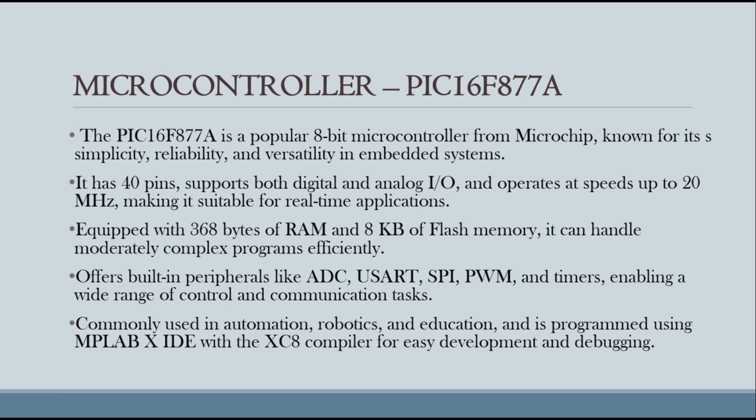Now we discuss the main component of this project, that is the microcontroller PIC16F877A. It is a popular 8-bit microcontroller from Microchip, known for its simplicity, reliability, and versatility in embedded systems. It has 40 pins, supports both digital and analog input-output, and operates at speeds up to 20 MHz, making it suitable for real-time applications. It is equipped with 368 bytes of RAM and 8 KB of flash memory. It can handle only moderately complex programs efficiently.